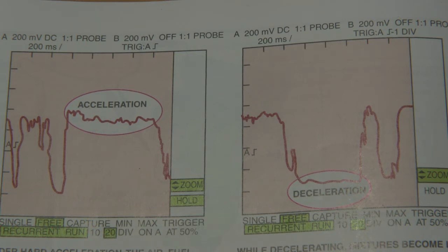And in this case, this example, an oxygen sensor, an upstream oxygen sensor that's bad, giving false information, false rich in this scenario, will no longer be affecting the fuel delivery when we go to wide open throttle. The oxygen sensor is taken completely out of the equation because it's not able to see that rich air-fuel ratio that we need under wide open throttle, because the manufacturers have just put a pre-programmed wide open throttle air-fuel ratio in. So there's multiple ways we can go about diagnosing oxygen sensors. This is just an example.